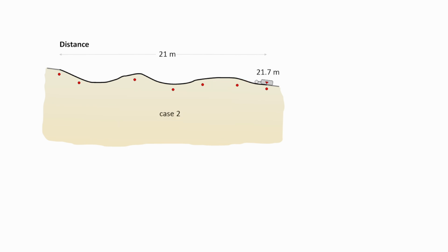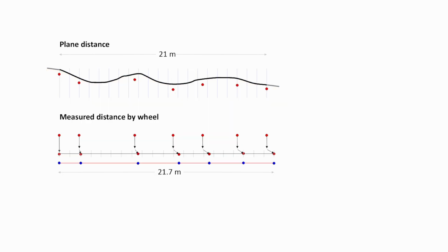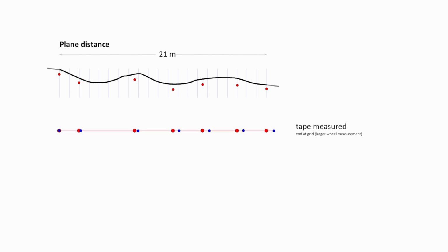If we take a measurement along a taut measuring tape, we'll obtain a longer profile. The difference, of course, comes from the fact that the terrain is rarely flat as a table, so the measured distance will generally be greater than tape measurements. Therefore, we should rather refer to this as the plane length. If we flatten the terrain curvature now, we'll see how significantly the locations of the detected objects change. The farther we move from the start of the profile, the greater the measurement error becomes.